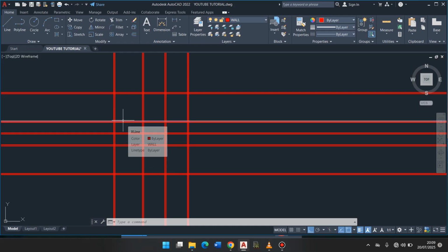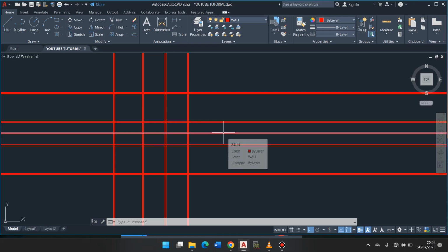And the next thing for you to do now that we've finished offsetting is to trim. Yeah, you have to trim off the unnecessary lines. The reason why we have to use construction lines in offsetting is just like in technical drawing. It gives you an idea of the limits you are going to, and then you can always erase those lines when you're done.